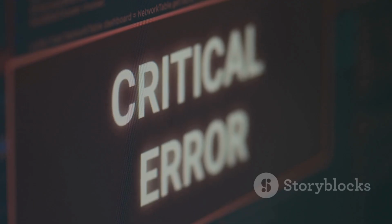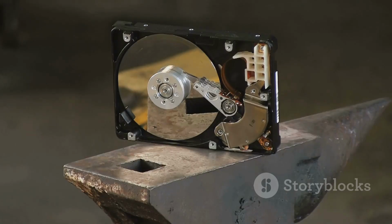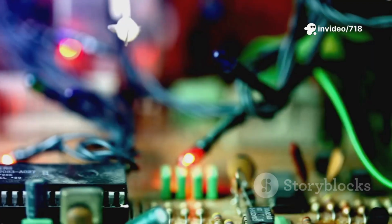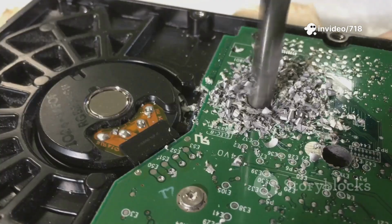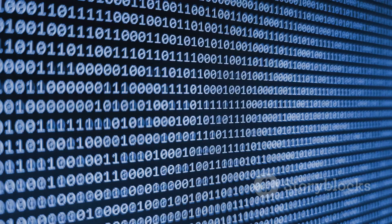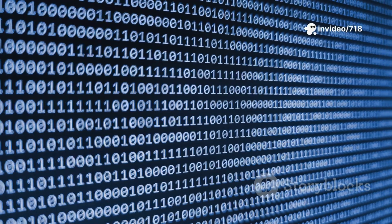Here's the catch, and it's a critical one. The read process is destructive. Think about it. To measure the charge in the capacitor, we had to empty it onto the bit line. The very act of reading the data destroys the original stored charge in the cell. The capacitor is now empty, regardless of whether it held a 1 or a 0 before. If we did nothing else, all the data in the row we just read would be gone forever.